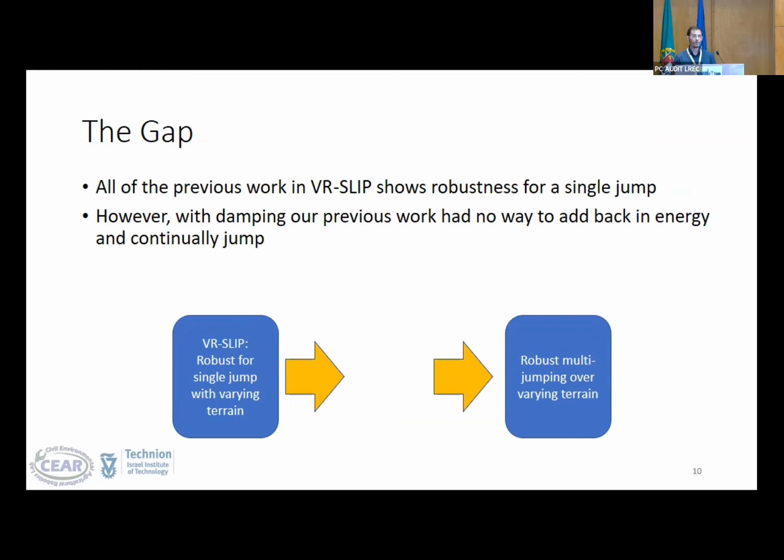So our optimization flow basically ends up going as follows. We take in our initial forward velocity, our initial height, and our target Y relative. We optimize the leg shape for stiffness and the SLR without damping. Since there isn't a great way to come up with the damping during a simulation, we then either find it in FEA with our leg shape that we generate, or experimentally by 3D printing it and putting it in a universal testing machine.